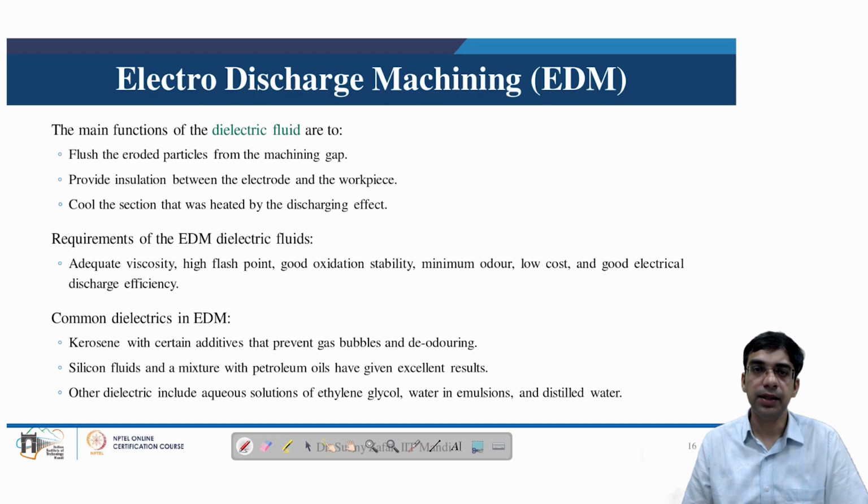Upon collapsing of this bubble, the dielectric fluid helps to remove the debris. Secondly, the dielectric fluid also provides insulation between the electrode and the workpiece. And lastly, an important function of the dielectric is to cool the section which is heated by the discharge effect.